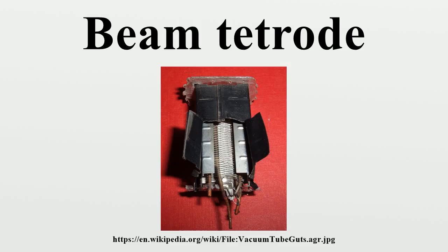In American radio receivers with transformer power supplies built from about 1940 to 1950, the 6V6, 6V6G, 6V6GT and miniature 6AQ5 beam tetrodes were very commonly used. In military equipment, the 807 and 1625, with rated anode dissipations of 25 watts and operating from a supply of up to 750 volts, were in widespread use as the final amplifier in radio frequency transmitters of up to 50 watts output power and in push-pull applications for audio.